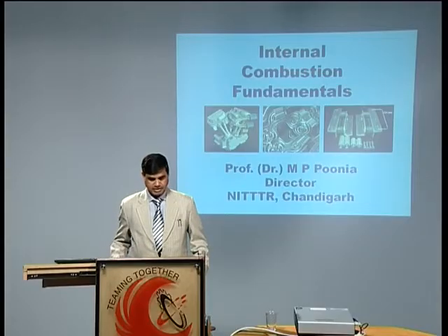At the same time we have discussed that for converting heat into work, the engine has to be operated in a cycle. A cycle may consist of 4 strokes, or a cycle may consist of 2 strokes. In a 4-stroke engine, when 4 strokes are completed, the crankshaft is rotated by 2 revolutions, whereas in a 2-stroke engine, when 2 strokes are completed, the crankshaft is rotated by 1 revolution.